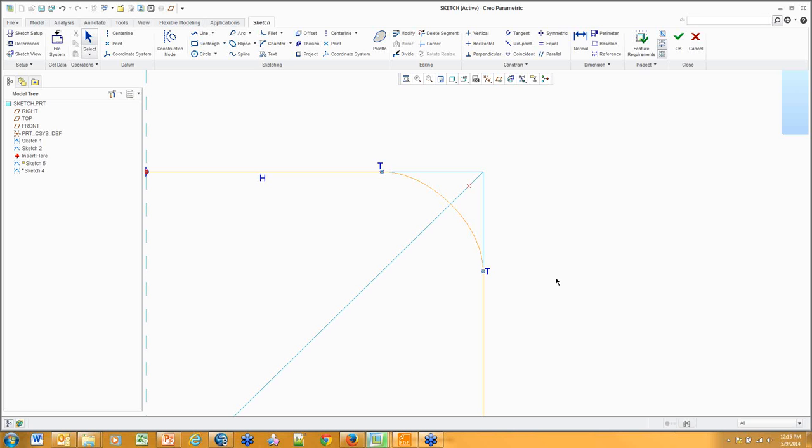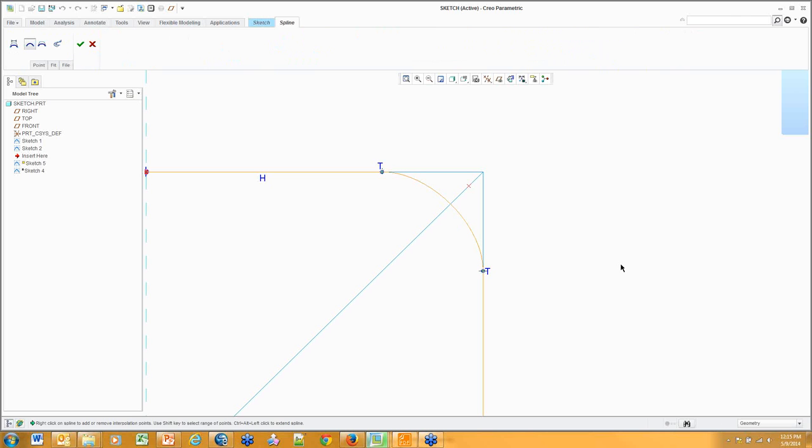That is not good enough for us. I'm going to double click on the spline. Oftentimes people will right-click on an area here and add a point. I'm not going to do that. There's a tool that I find everybody kind of overlooks. It's here on the left. This is going to put us into polygon mode. What that means is we can edit the values of the spline while not in the spline tool.